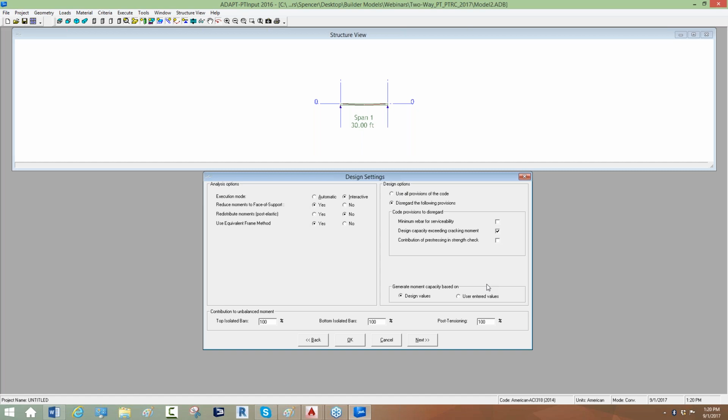Whenever you model something, you model a slab, a beam, you model loads, post-tensioning, the program will always calculate the amount of rebar that is necessary to meet the demand moments or factored moments relative to the strength combinations in the program. And it will report in the summary sheet what rebar you need to add to a system in order to meet the demand.